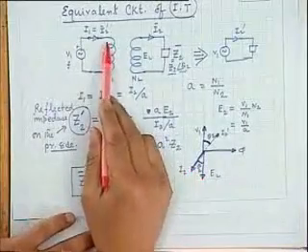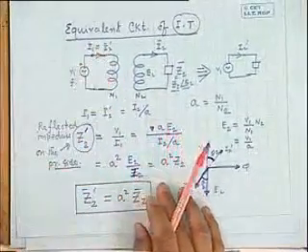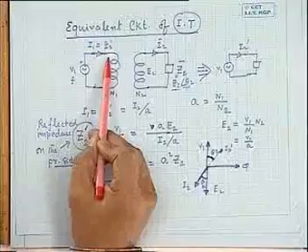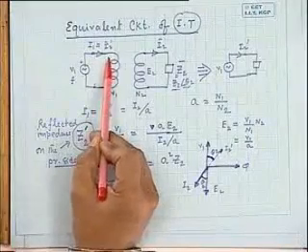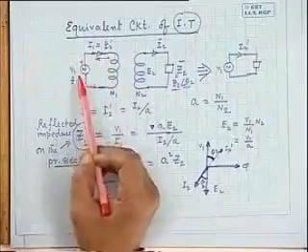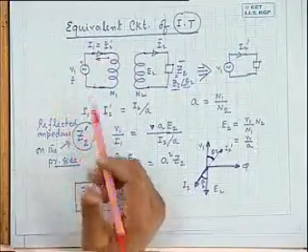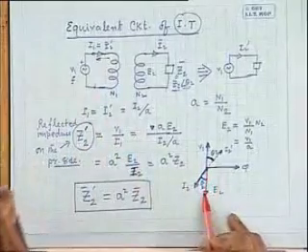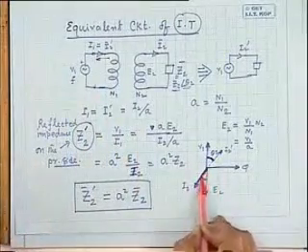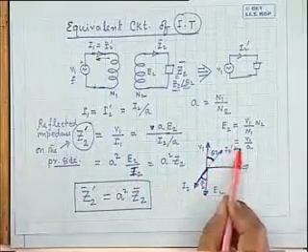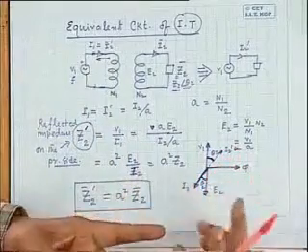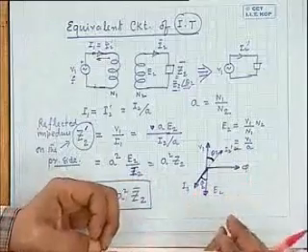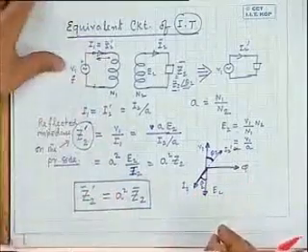They draw it just to show that the voltage induced in, say, the primary winding, if it was allowed to pass some current, would have pushed out power from the winding to this side. Any induced voltage is in opposition with V1. Just to convey that, they show it 180 degrees apart. Similarly, I2 dashed they draw here in order to show that the MMF cancels out. Nothing more to it.